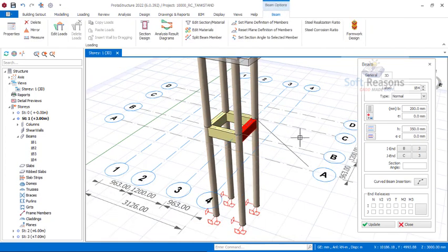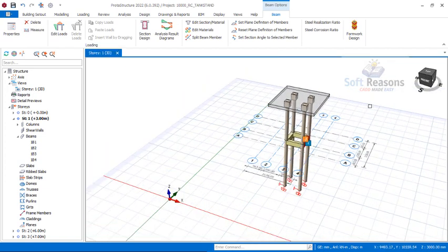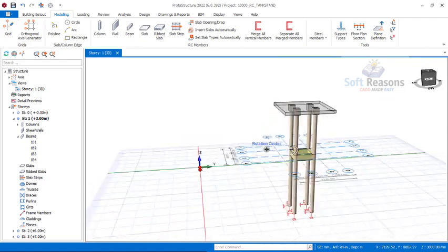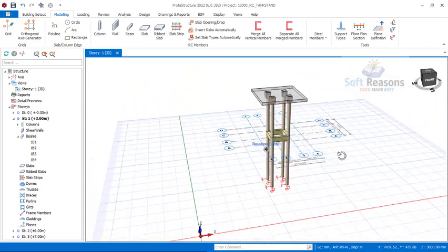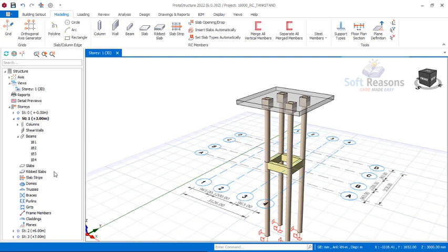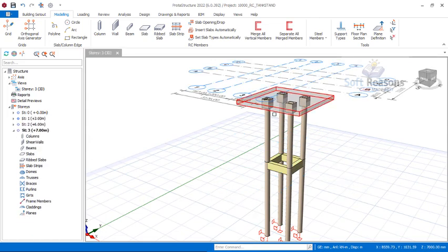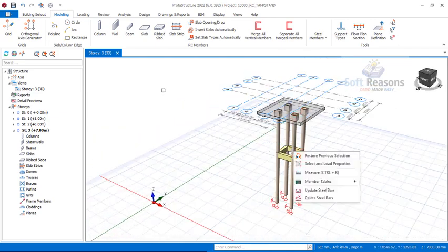All right, it's not actually carrying anything that much. Okay, so we close that. Let's close that. So now we are having this just like this. Okay, the next thing I will show us how to model is the railing on the top of the platform. Okay, so to do that, you navigate to the story tree right there, and then at this story tree, just like this, you go to the plan view.